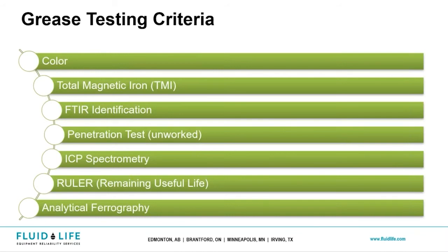So here is what we would call our wind-related grease testing criteria. This is what we call our advanced test package. We do have varying types of packages that you can investigate, especially if you know other factors like cost, of course, and scope and how you perform your O&M. But here we find that based on application of large diameter bearings with rolling elements, right? You're talking about tapered rolling bearings, cylindrical rolling bearings. Those applications tend to fall in line with this testing itself, right?